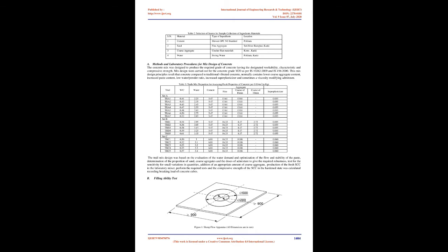2. Material and methods. Self-compacting concrete, SCC, is an innovative concrete that can hold sufficient workability without any vibration. It is able to flow under its own weight, completely filling formwork and achieving full compaction, even in the presence of congested reinforcement. The hardened concrete is dense, homogeneous, and has the same engineering properties and durability as traditional vibrated concrete. Addition of rice husk ash as cement replacement in SCC provides enhanced characteristics.